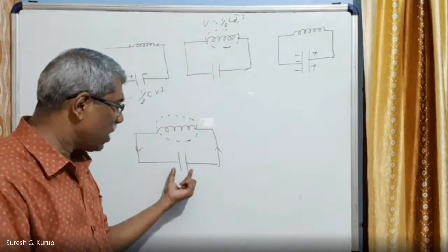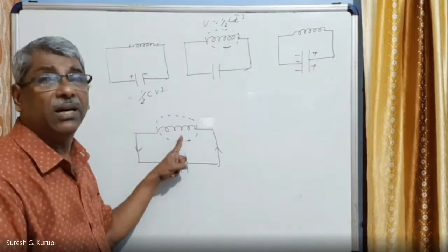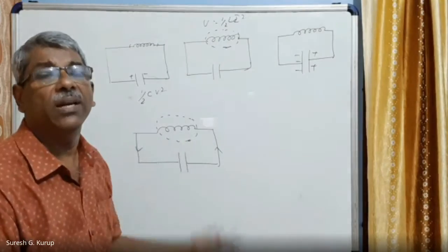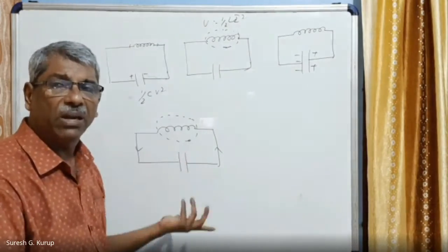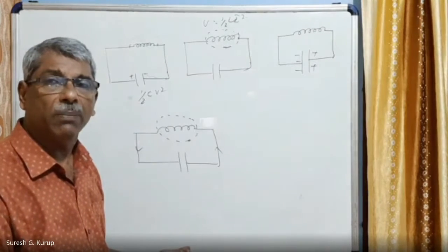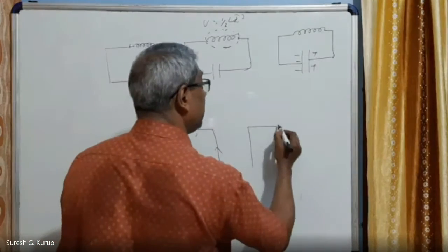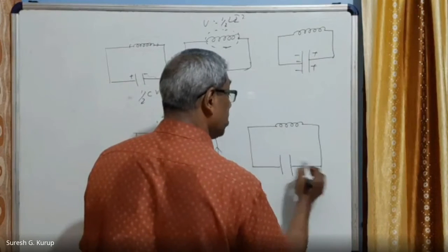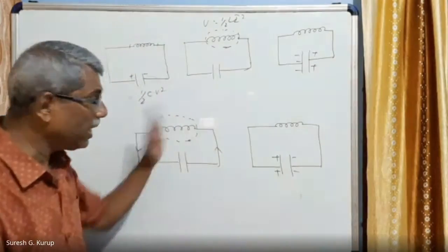Now there is no charge to come from the capacitor, so again the magnetic flux inside the coil starts decaying. Decaying magnetic flux will induce an EMF in the coil that will charge the capacitor oppositely. That is this condition. So the capacitor is getting charged as it was, this becomes positive and this becomes negative. This is the next half cycle.